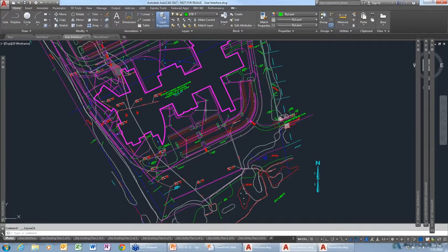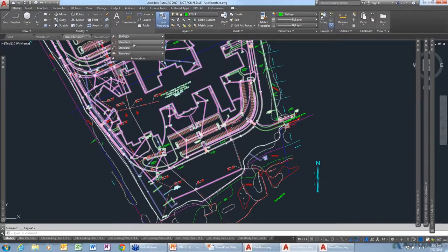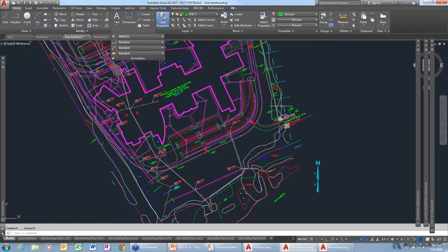So I noticed when you had that tool, you had to select the little drop down to get to it. Is there a way to keep something, like maybe I want that annotation panel to always be open as opposed to having to select it each time? Yeah, there is. If you click on the drop down here, you'll see a little pin icon. If we select that, it's going to pin that panel open so we can use it while we're working on our drawing.